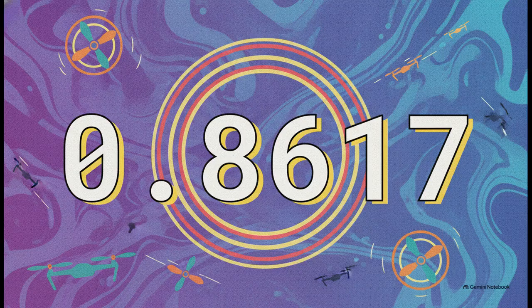Let's actually anchor this concept by looking at 5,000 feet. At a 5,000-foot altitude, the density ratio is exactly 0.8617 compared to sea level. That means the air is quite literally almost 14% thinner. You kind of have to imagine the air as a fluid that the drone is swimming through. At 5,000 feet, that fluid is substantially less dense. So the propellers literally have less material to push against to generate thrust.